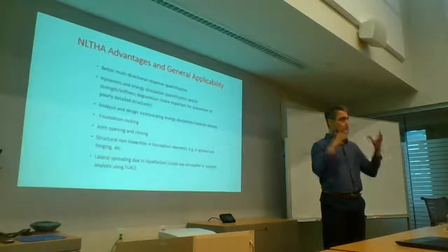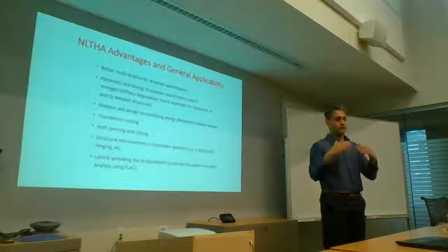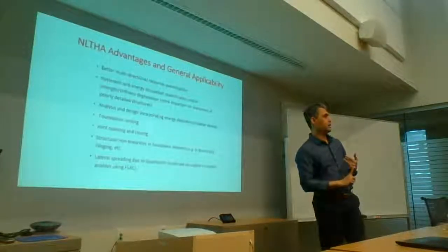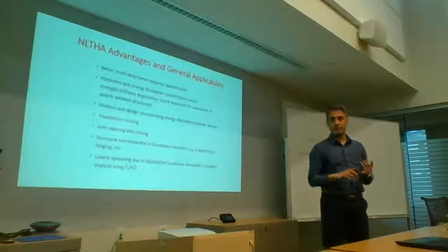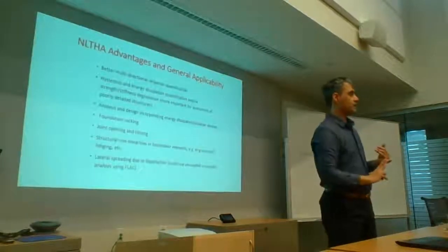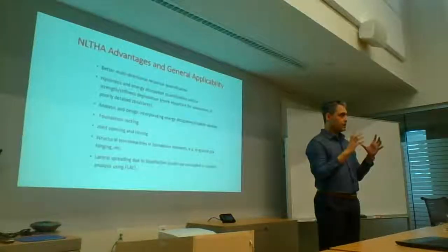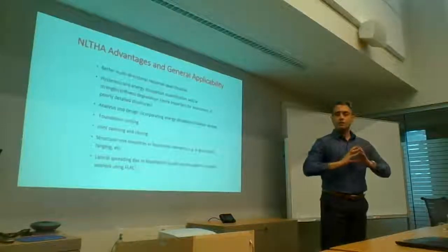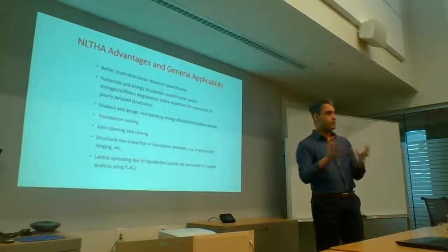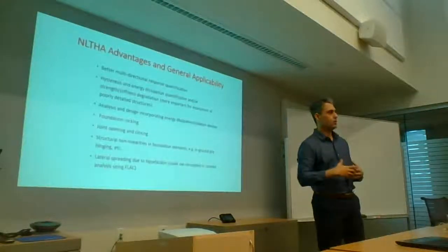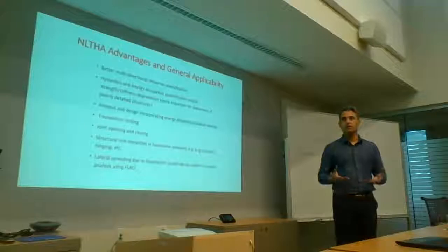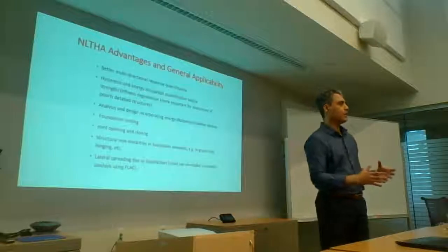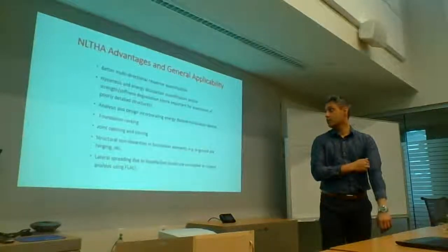Okay, so once you've understood your failure mechanisms and their hierarchy, the hierarchy is very important. Is it going to be joint shear that's going to come in first? Is it going to be the foundation that's going to fail first? Is it going to be column shear that's going to really be a problem? Then you start to think about the solution to that problem. Okay, and now to demonstrate your performance after you've retrofitted it is a lot better. And now the time history may be a lot more meaningful. So you've got to hone in or zone in, focus on those problems and not just keep running analyses that don't give you a lot of value.